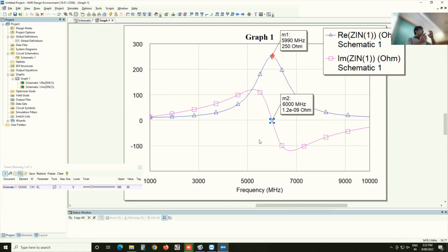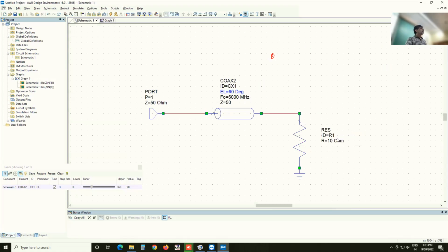So this impedance transformation, which is happening, I've used this term for the first time because essentially you can think of what this section of transmission line is doing is it's transforming the original load into a new load which has both real and imaginary parts. Remember, you started with only a real load here, 10 ohms, real, right? This is a resistor.